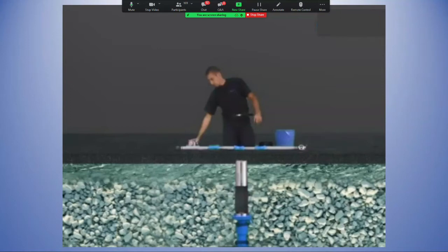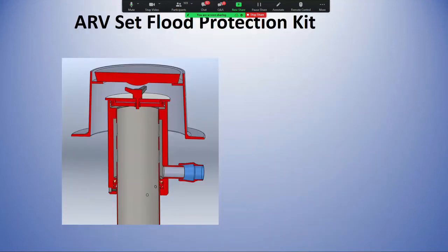And they say, well, it's meant for wastewater because it has stainless steel internals. Well, fair enough, I get that. You have a corrosive environment, but you haven't accounted for the larger solids that are going to be in that wastewater line that could very well interfere with the way that valve performs. So it's very important. I just want to make that note.